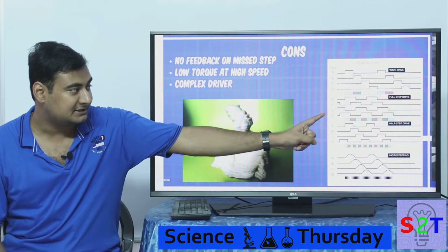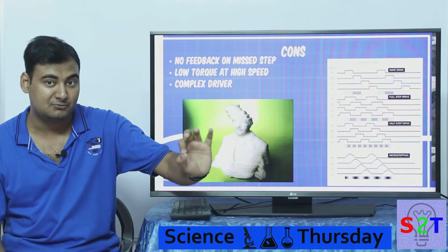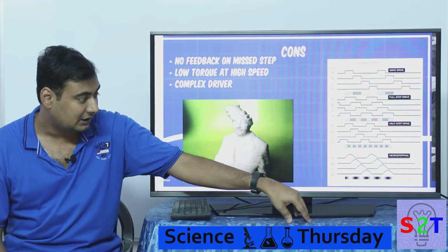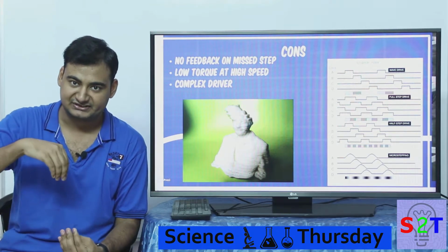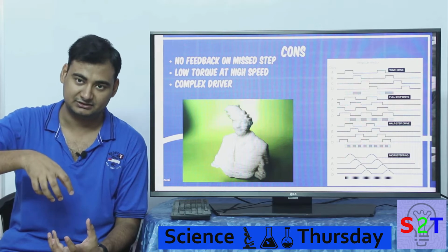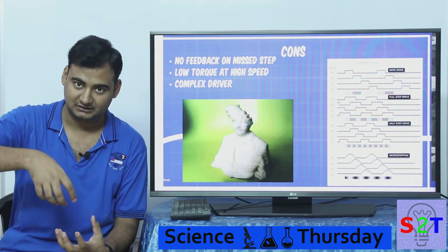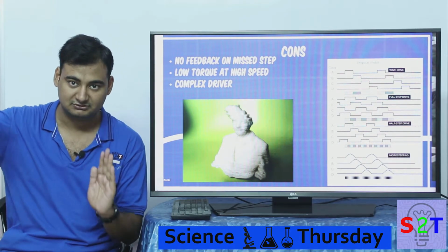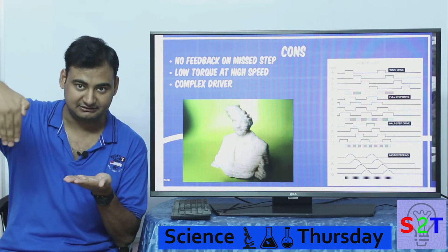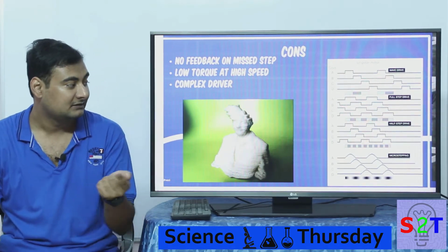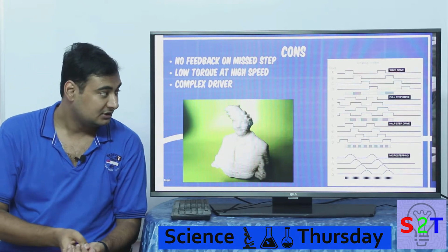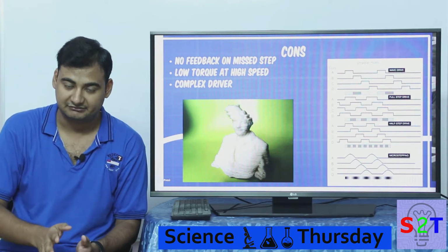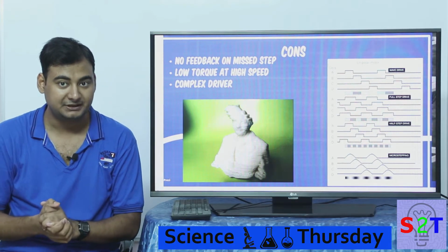Like for some applications where torque is of the utmost importance, you're gonna use full step, and in some places where you want silent operation, let's say you're doing a laser cutter which does not have any torque application to it, like it does not resist. A laser has no resistance, while a CNC milling bit has resistance. You might want to use micro stepping. That will also increase your resolution. So it's not that you can use one with everything, but you have to pick and choose.